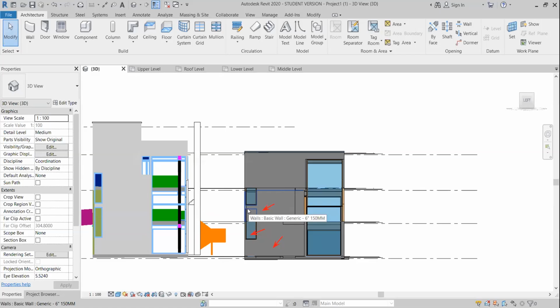That's why this wall is still appearing, which means in this area the wall should be a big one like this, so you can host the windows without any problem. Any window should be hosted only in one wall. It should not be like this. There is another wall here, so it will overlap in this case. Same thing, it's overlapping here, which means you need to create a big wall like this in this area. Okay. So you have to try to fix these things.